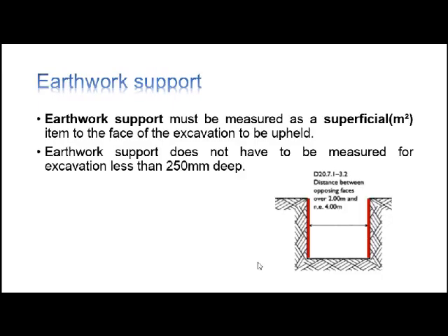So going further, after you are able to excavate the trenches, you take up that particular item. In reality, you should put the earthwork support. So earthwork support can be made up from wooden, okay, or timber. So if the type of soil is quite weak, you need to have a timber support on both sides of the trenches.